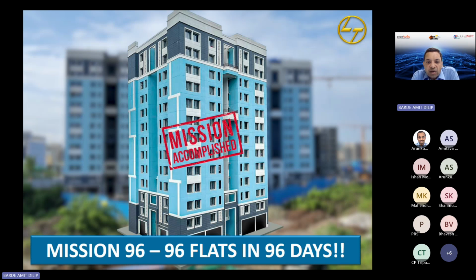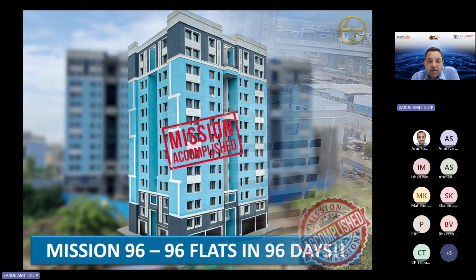And the 3-day number was not important. What was actually more important to us was that the first floor itself was done in exactly 3 days. And then each floor, all 12 floors, were built in exactly 3 days. And that's very unique in construction because of the site challenges and all. To perform consistently is one of the biggest engineering challenges these days. And we were able to showcase that, okay, if you give the resources, because most of the work is already done at the factory and brought to the site, we can control it much better and we can deliver. That assured delivery is probably of more importance here than the speed itself. With precast, the speed is a given.